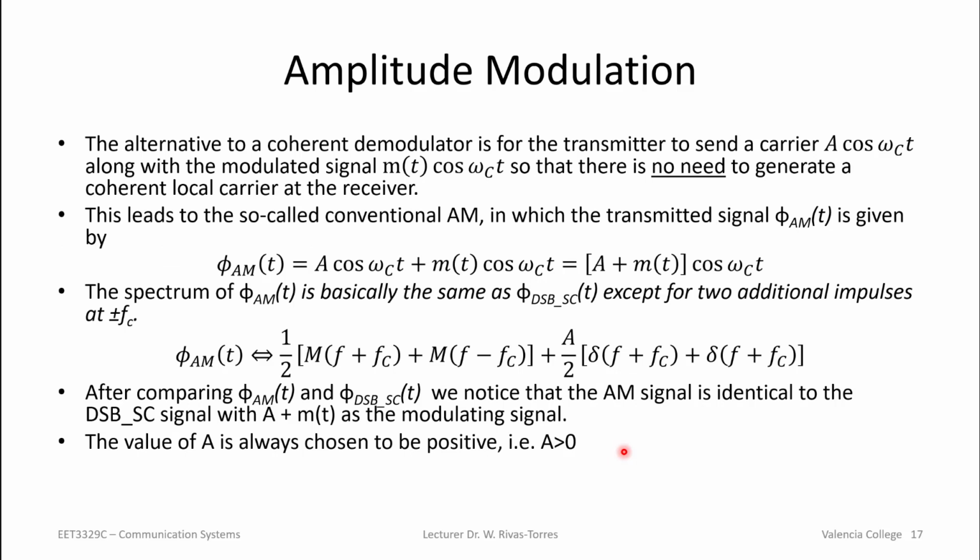And that's amplitude modulation, by the way. Notice that I'm saying AM: no suppressed carrier, no double sideband, none of that, just pure AM. So the alternative to not having to have a coherent demodulation process is for the transmitter to actually send a carrier. Come on, you know what the carrier is, right? Just because I didn't put something at DC, you're not going to send me the carrier? Come on. So if we could come up with a way to do that, and not depend on the kindness of the transmitter, we could avoid this requirement. And there is such a thing.